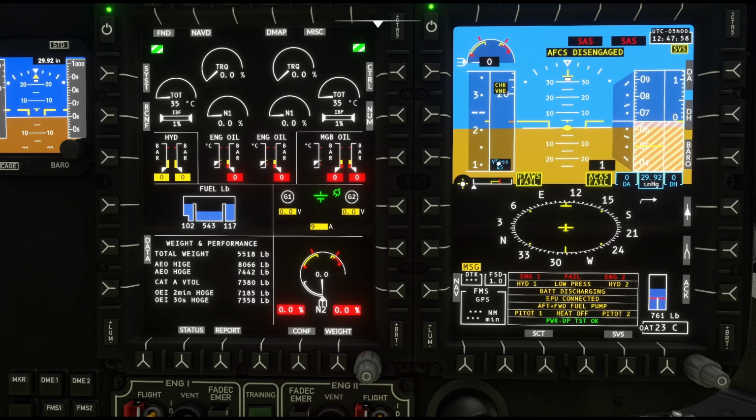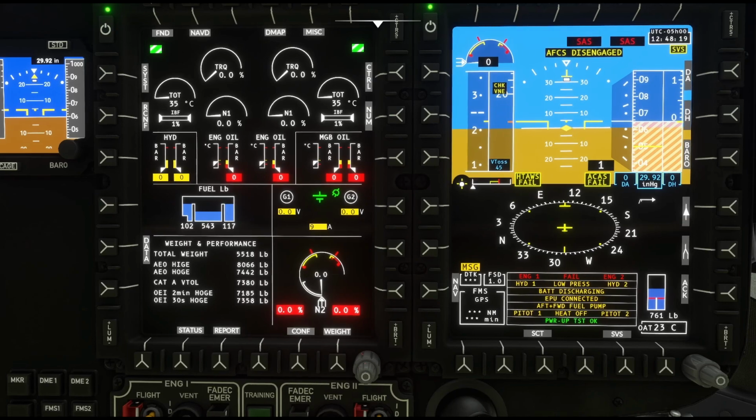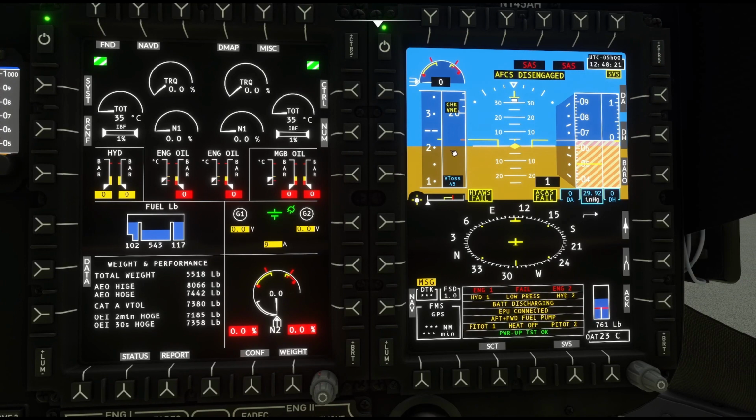All right, so at the bottom of this right now, it's telling me V vertical, my takeoff speed. VX is 45 knots. That is your maximum rate of climb per distance X across the ground. The other value to be aware of that's similar to this is VY. That's your maximum climb rate. That's the fastest rate of climb that you're going to get because it's the most efficient speed for the rotor system. All right, so the next thing we get into right here is your attitude indicator.